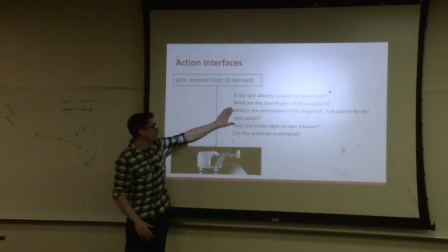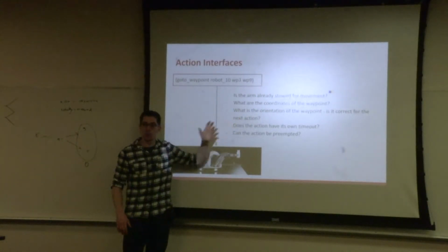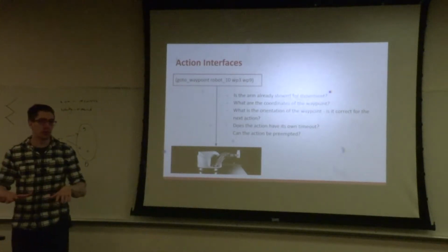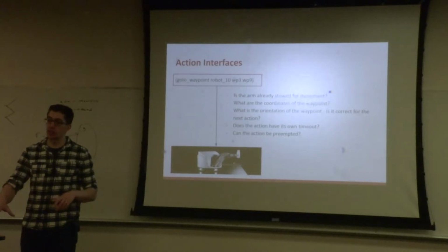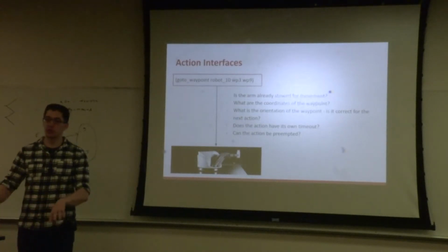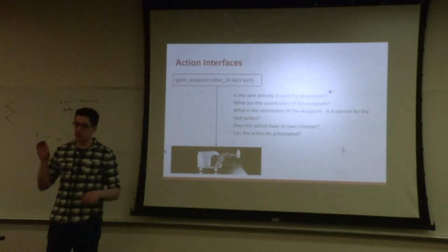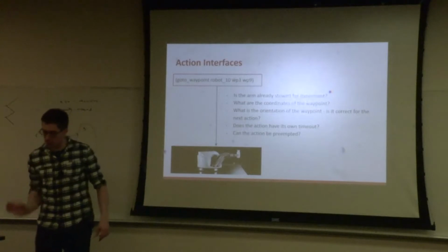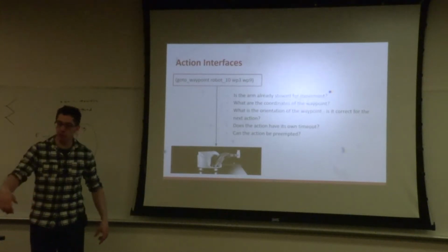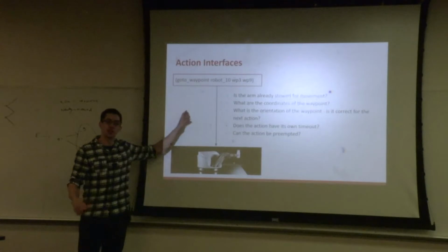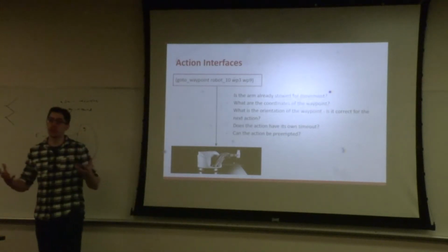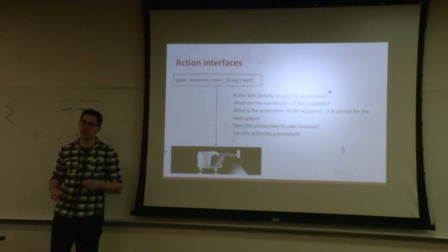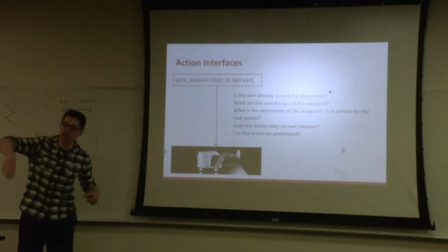Going back to this third one, a very nice example of why planning is useful is this scenario I've seen before of cans on a table that the robot has to pick up, but there are many cans obstructing the one in front of it. One solution, the robot might be able to have two different grasps, one where it grasps from the top, one where it grasps from the side. It could probably grasp from any angle. All you need to do is call MoveIt, the motion planner, please grasp this object, and it will figure out how to reach around the cans and take the can.